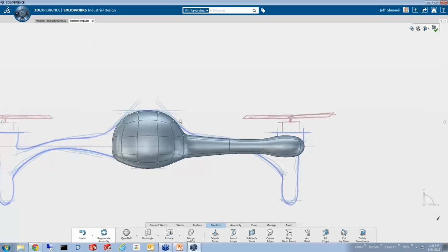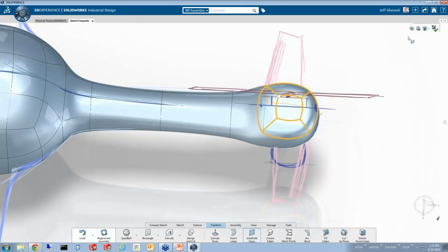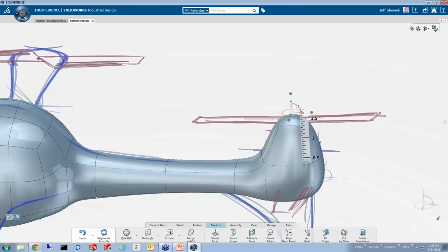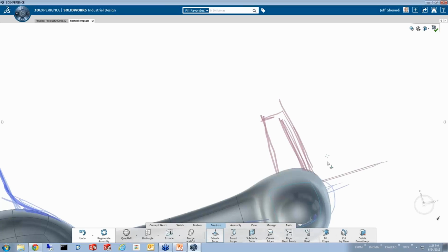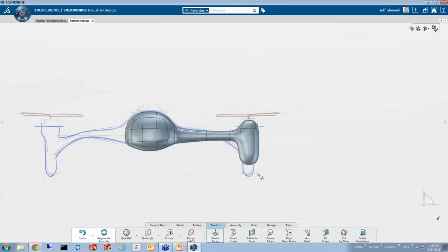So we get the general shape that I'm looking for. Maybe pull this surface up a little bit here. And then I'll add some additional faces here. If I subdivide this face, it gives me a little bit better control of that particular face. I've basically made a picture frame there. And I can take a surface and pull that up, for example. Take some on the bottom. Maybe I'll extrude this face and add a couple more loops to it.